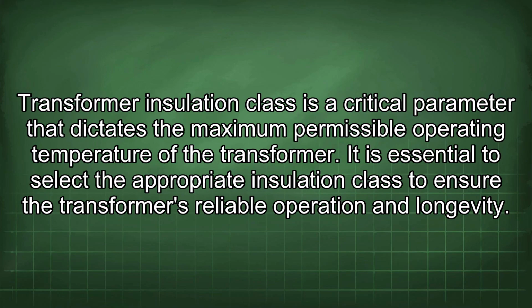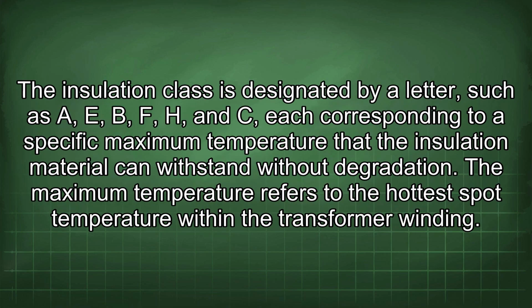Transformer insulation class is a critical parameter that dictates the maximum permissible operating temperature of the transformer. It is essential to select the appropriate insulation class to ensure the transformer's reliable operation and longevity. The insulation class is designated by a letter, such as A, E, B, F, H, and C, each corresponding to a specific maximum temperature that the insulation material can withstand without degradation.